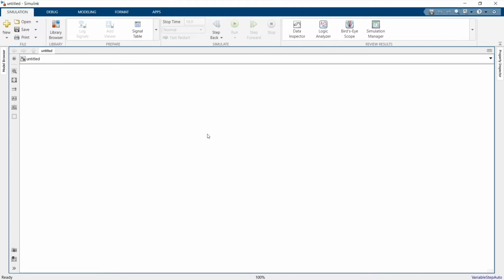parameter edit block. So now we will be adding a DC voltage source. Let me edit the properties of the DC voltage source. We will use a 32 volt DC voltage source. Why do we require 32 volt? Because we will be using a boost converter in order to boost the voltage of this DC voltage source.